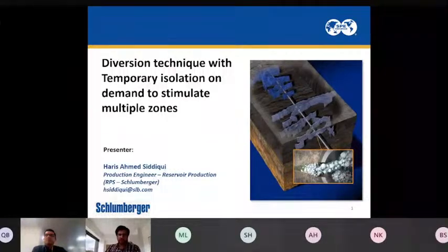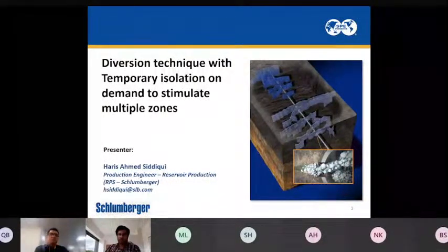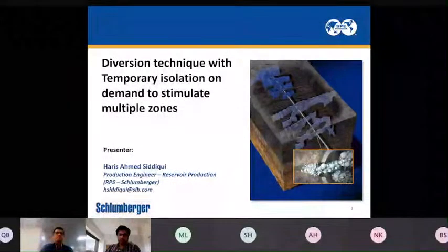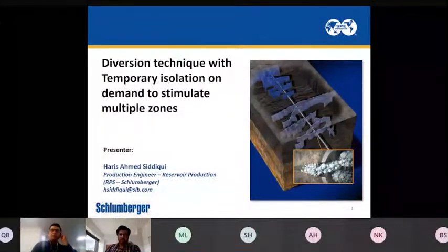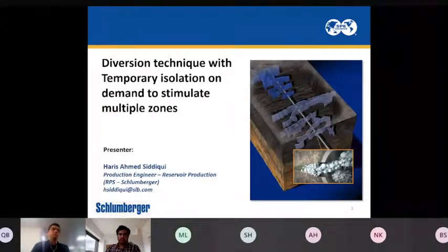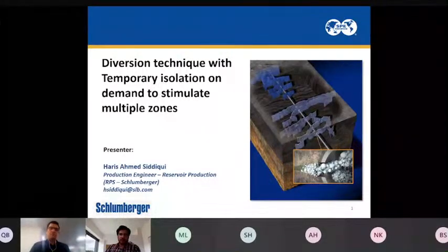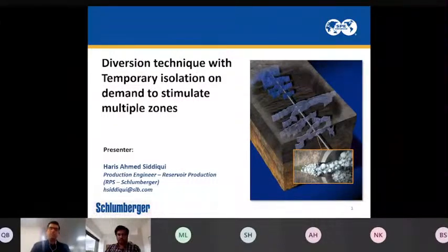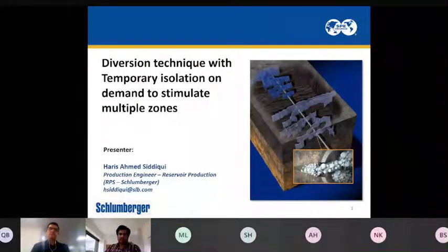If we use the composite pill, the degradation won't leave any residue or anything behind. So in terms of cleanup, obviously it will be efficient and easier for us to flow back. Again, it depends on the objectives of the operator, how long they will take to flow back, how efficient the system is in the well, and how the techniques and placements are in place.